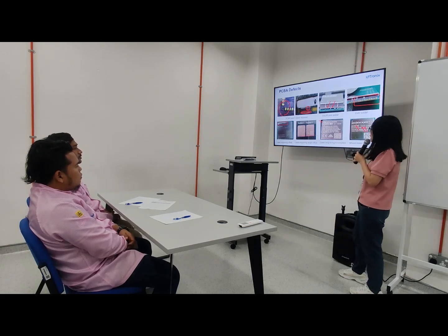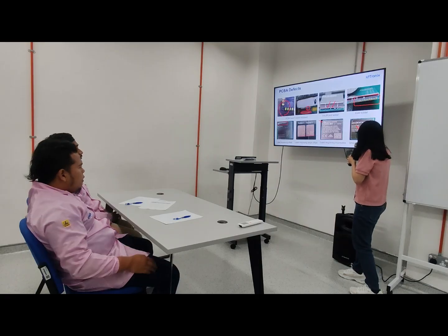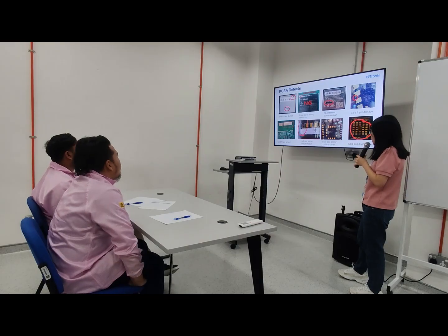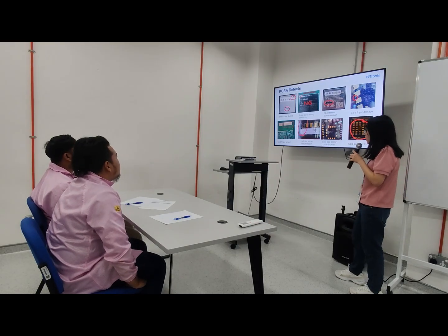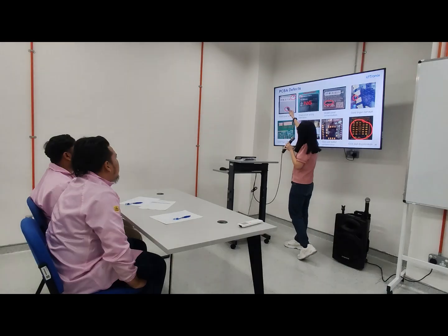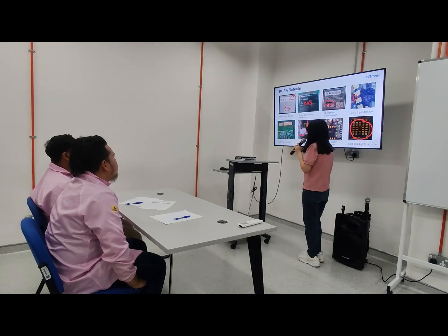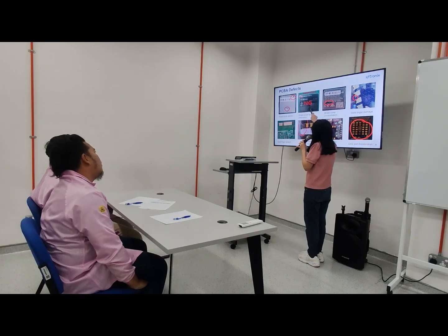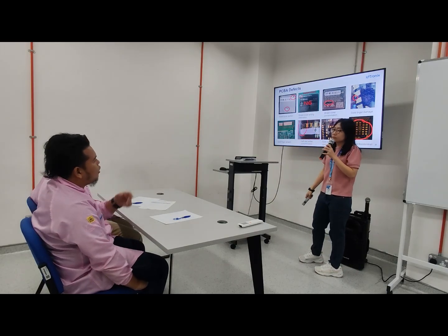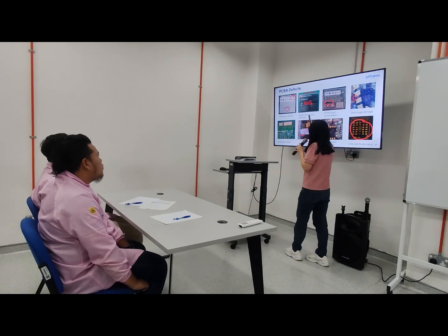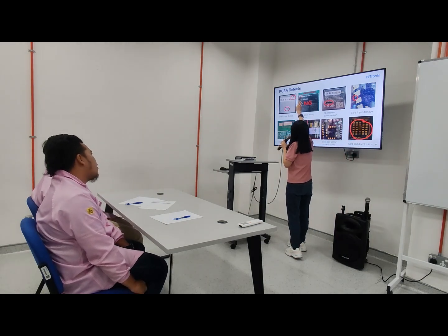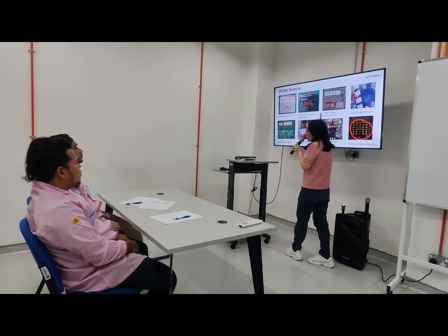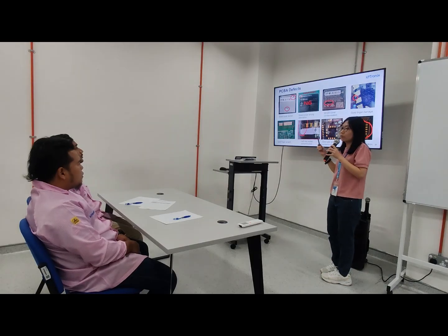Okay, shear cover scratches. Scratches like this, cannot. Okay, next we will go for shear cover dented. This one I think quite obvious. Then this one, shear cover wrong orientation. Can someone explain this one? Why is this wrong orientation? Yes. Supposedly, if correct, we'll see the hole here. This one we cannot see the hole, meaning the shear cover was put in the wrong orientation.